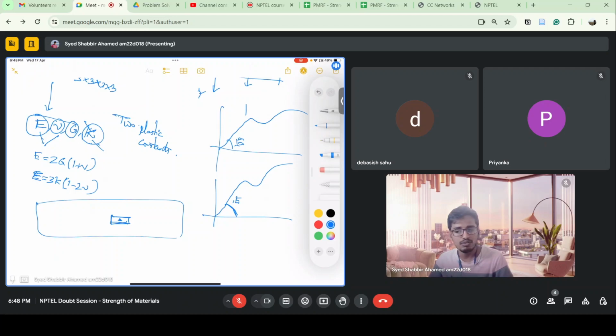But if I take a wooden bar, and apply load along the direction of the fiber, I'll get a very high Young's modulus. But if I apply it perpendicular to the direction of the fibers of the wood, it will fail easily. So E will be different perpendicular to the direction of fibers, and different parallel to the direction of fibers when I apply the load. So that is not an isotropic material. In fact, wood is considered orthotropic, because I have Ex, Ey and Ez, since perpendicular to the fibers, I can apply the load in this direction or also in this direction.